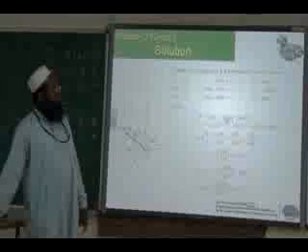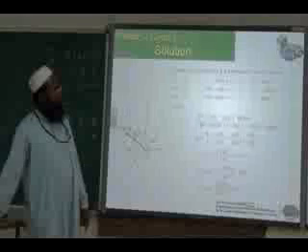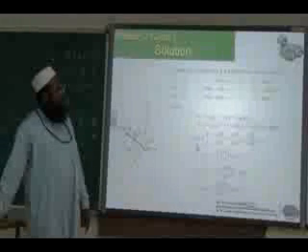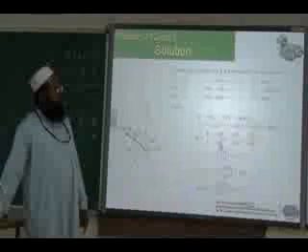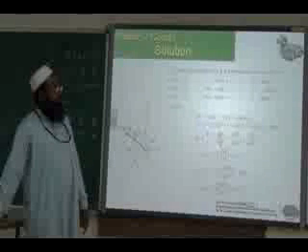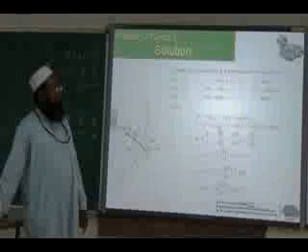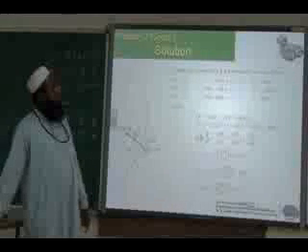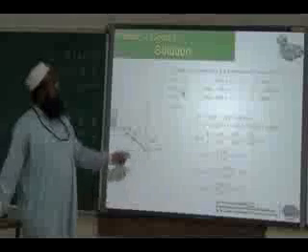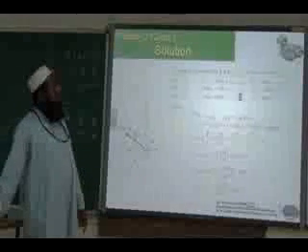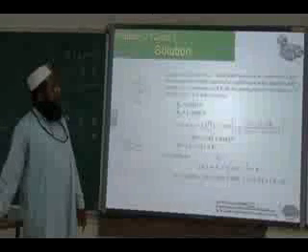So we can write it in the IJK format, and the direction coefficients can be obtained using the unit vector concept. UF equals F divided by the scalar magnitude F, so 200I divided by 300, the magnitude of the force. So we get alpha, beta and gamma. We apply the equilibrium concept and find the unknown force after resolving it into components.